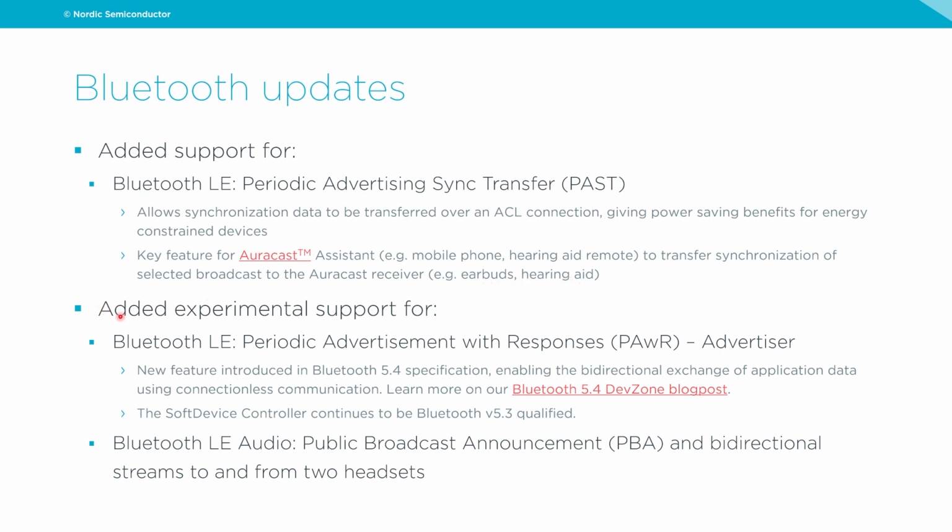We have also added experimental support for a new Bluetooth 5.4 feature called Periodic Advertisement with Responses. We added support for the advertiser role here. And the key thing is that this enables bidirectional exchange of application data with connectionless communication. So before this, using advertisement or connectionless communication was one way, and now this can be bidirectional.